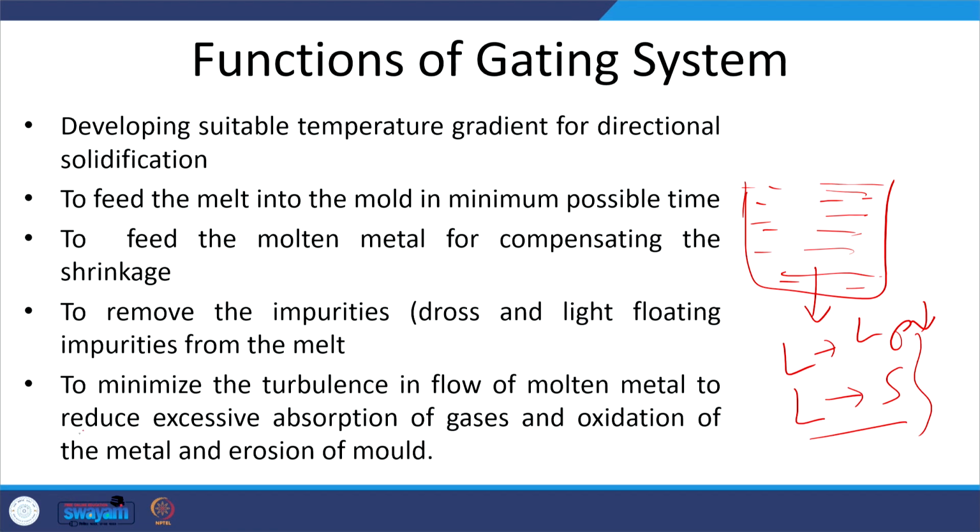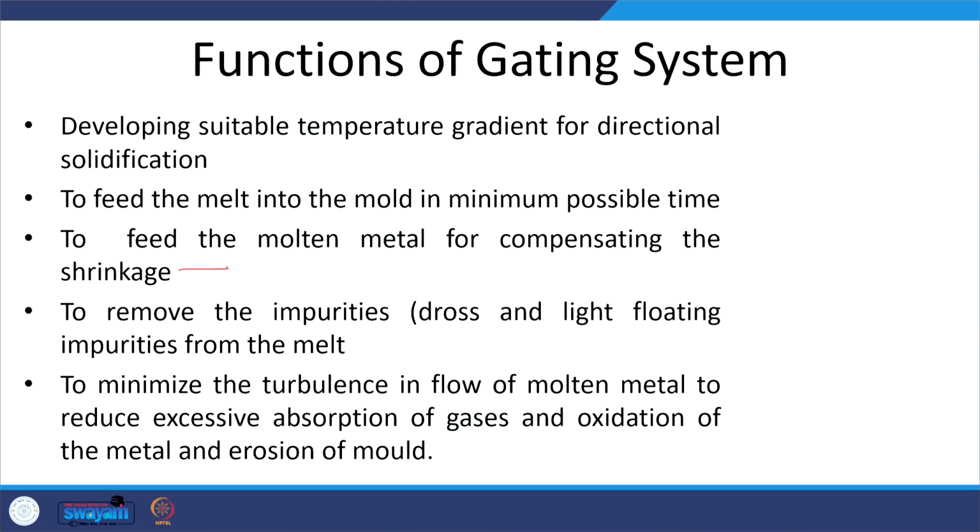Both types of shrinkages must be taken care of by the gating system, and that role is performed by the riser.